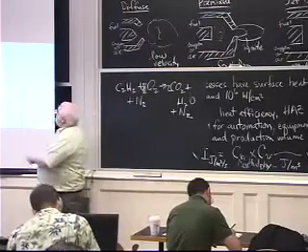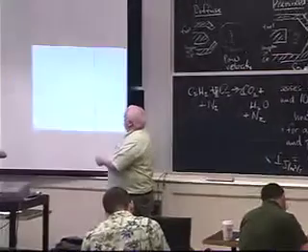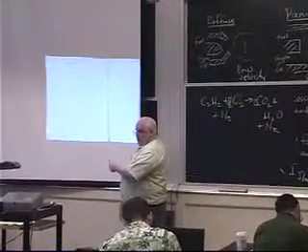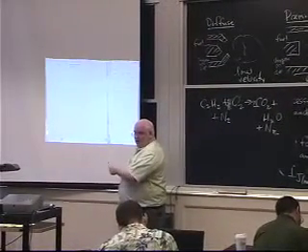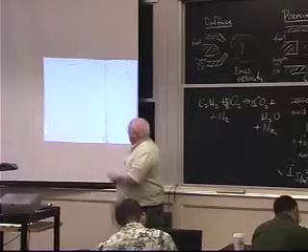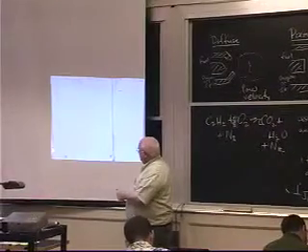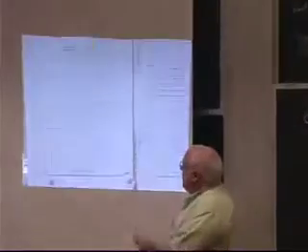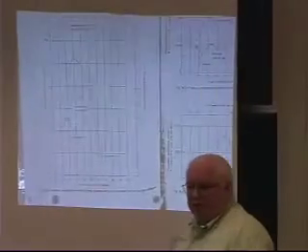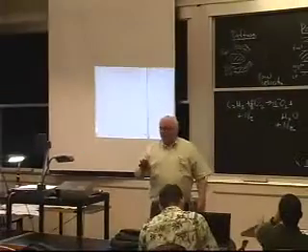So I end up with these types of plots where if I'm at stoichiometry, I'll get the maximum temperature or maximum burning velocity. They go together. And you have these plots in your handouts. That's how I get my maximum temperature. That's how I'm going to get my maximum heat intensity for burning. Someone said they were confused before.